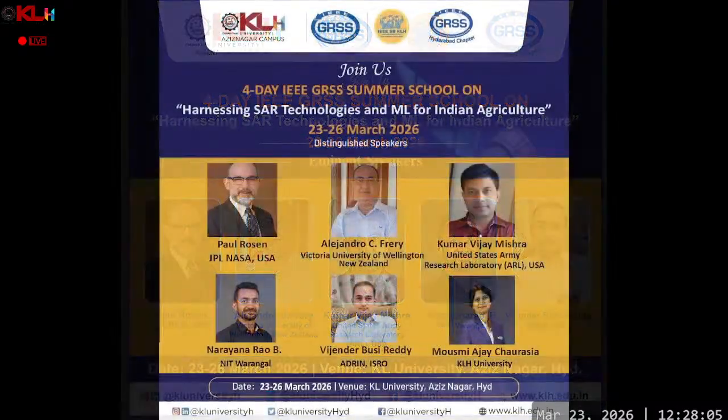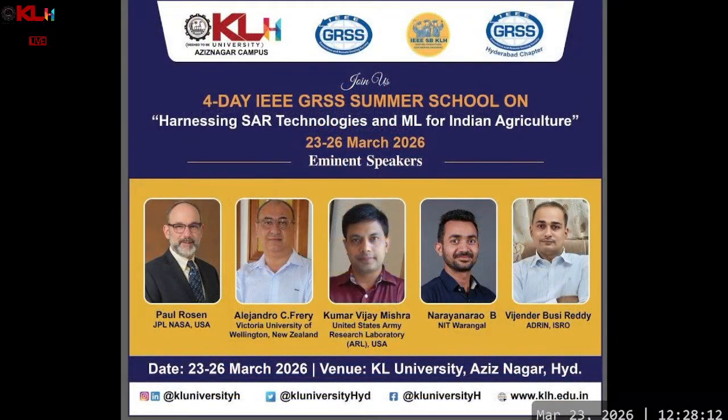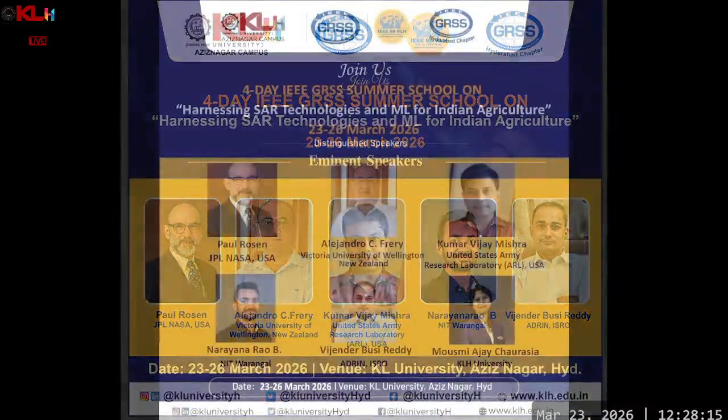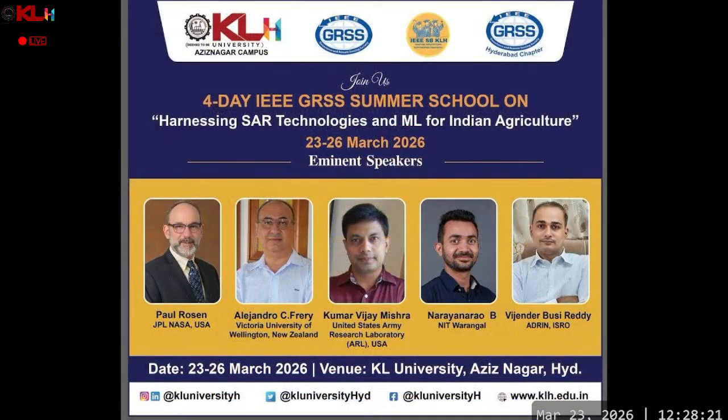Okay, I don't know anything about other SAR data, but I know if you're using QGIS with NISAR data, which is in a specific format called HDF5, at the moment you need to do a few little tricks to get it to be read properly. One is you can take the file name and change it from .h5 at the end to .nc. In theory, I've been told, QGIS can read that. If you want to spend the money on ArcGIS, it already reads it. You don't need to do anything. So if that's what you mean by different, I think that's the trick for getting NISAR data to work.